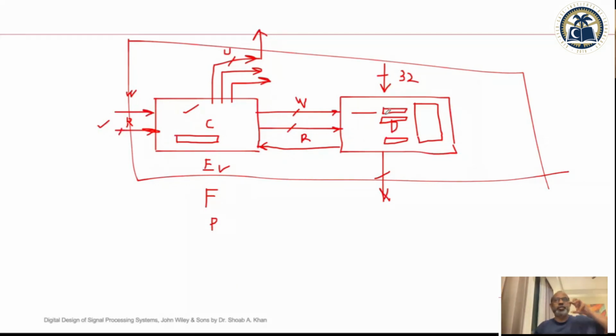So FIFO is written by somebody and read by somebody else. So he says read me, and it says there is an underflow, there is nothing in the FIFO to be read. Okay, so full is if the person writing has not been read from, and the FIFO is full, and he writes another thing, and it says, oh, there is an overflow flag.